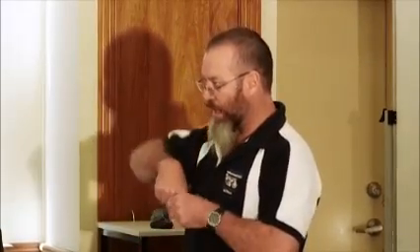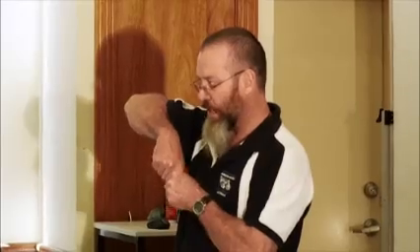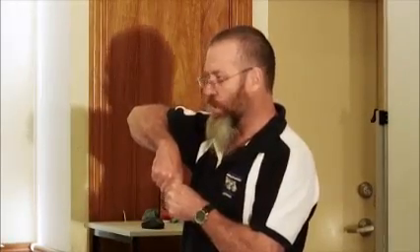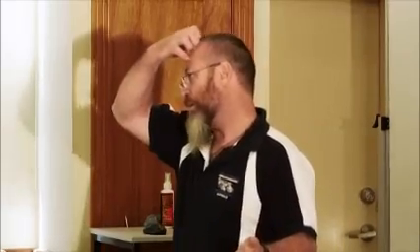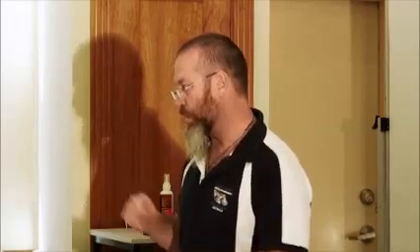So the ironbark has a very, very high ability to hold that fixing. Therefore, you don't need a fancy fixing. Instead of using a deformed shank nail, a twist shank nail or something like that, you'll only need a plain shank nail. So that's why we need to know about joint groups. And then we go and select the tie-down connection. And basically there's a whole series of tables that we need to go through. But basically, if I've calculated 2 kilonewtons of resistance for argument's sake, we need to go and find a connection that is equal to or greater than that 2 kilonewtons of resistance. It's as simple as that.